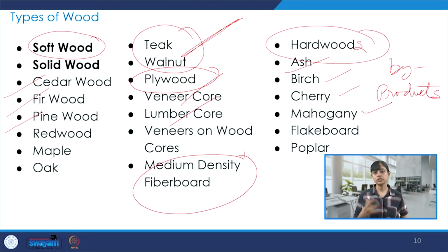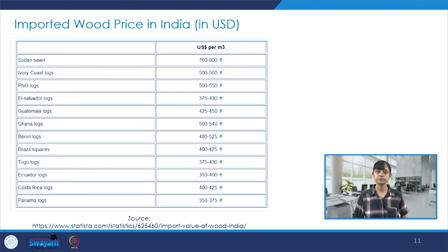And of course, it will come only after a lot of experience in working on site and touching the material, using it, trying to learn through the method of cutting, whether you want to cut along the grain or across the grain. Along is always more advisable to maintain strength. So all of these, theoretically speaking, give us some awareness, but there has to be a practical understanding which will help us understand these materials much better. And then we can utilize them to their full potential and execute them in the best way possible.